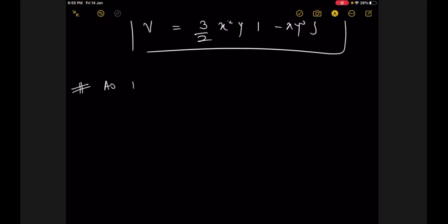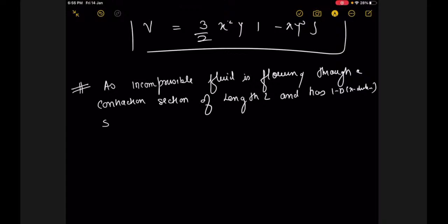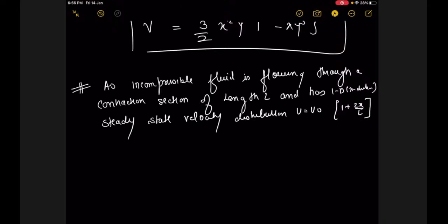Next question. An incompressible fluid is flowing through a contraction section of length L and has a 1D, x direction, steady state velocity distribution u equals u naught into 1 plus 2x by L. If u naught is equal to 2 meter per second and length is equal to 3 meter, the convective acceleration is...